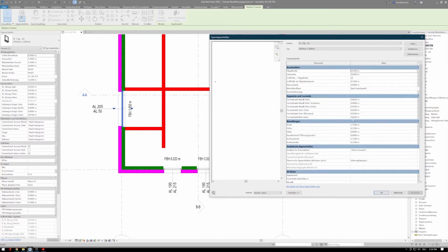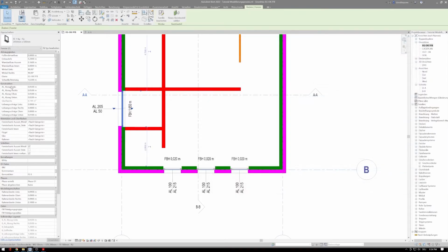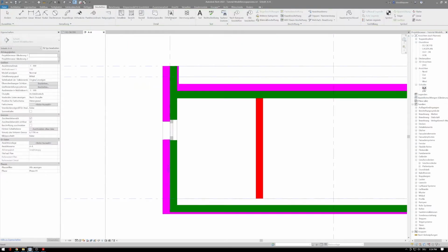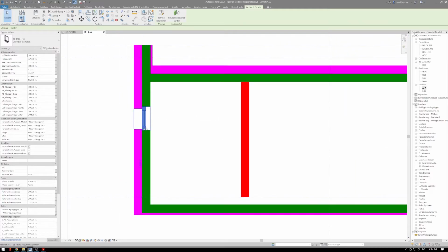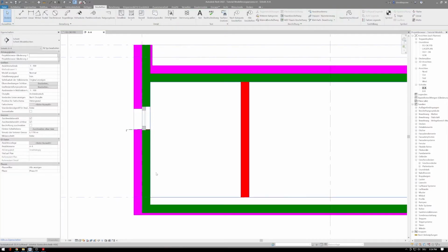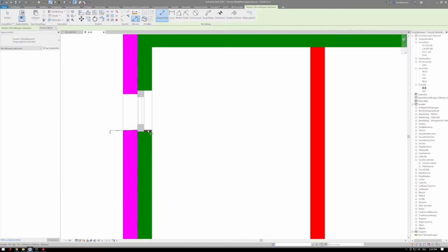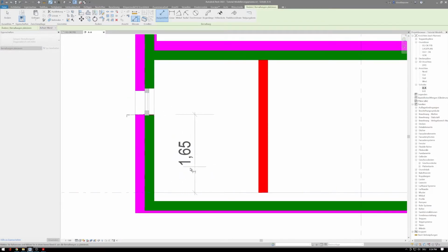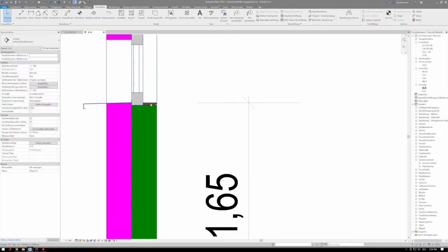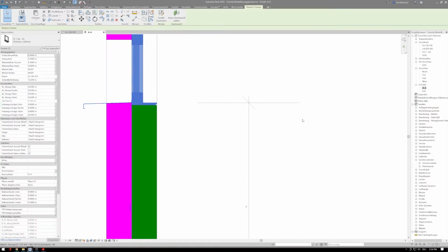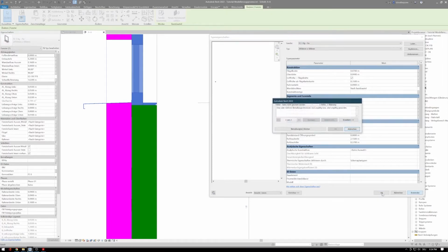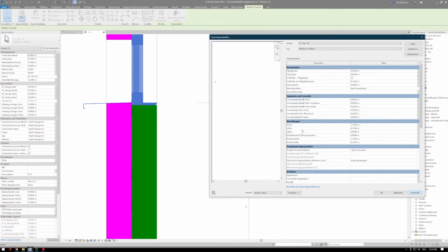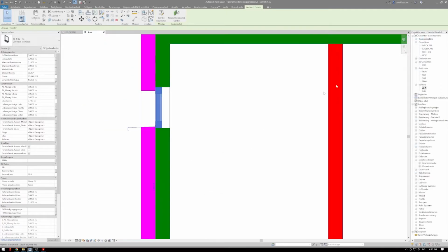So it's 0.02, and my Schwelle Brüstung parameter is set to take it from the Brüstung from the Fensterbank. Now, if I go to detailed view, this is where my Beschriftung actually reads. So in this case, if I make this parameter 0, it actually solves my problem.